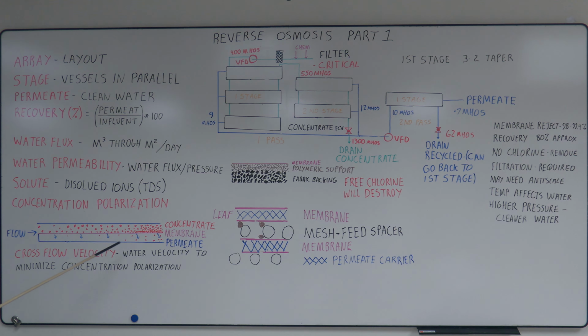This is part of the whole thing, concentration polarization. All these items up here pertain to concentration polarization. You bring your water in, the clean water goes through the membrane, and the dissolved ions or minerals are left behind. As the water comes out, you develop a layer along the membrane surface, which, if it gets concentrated enough,